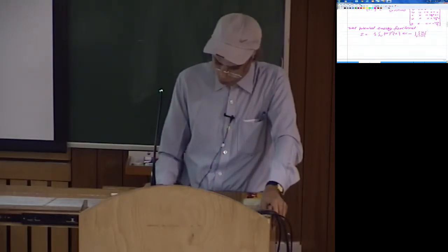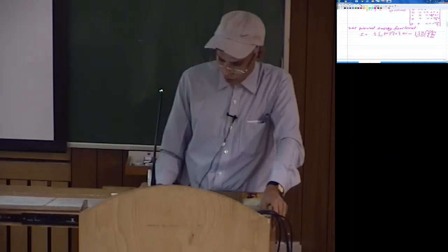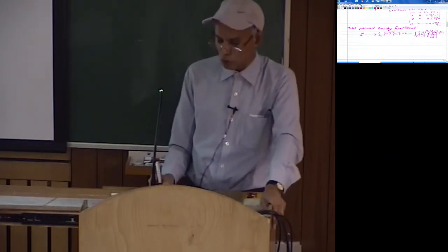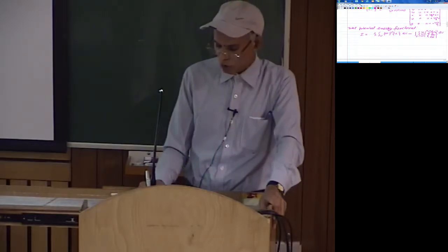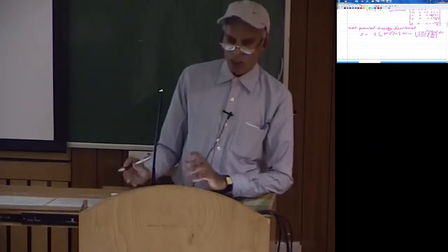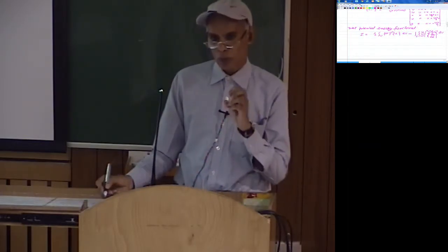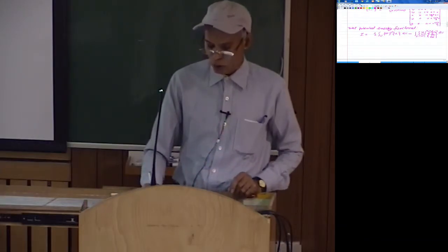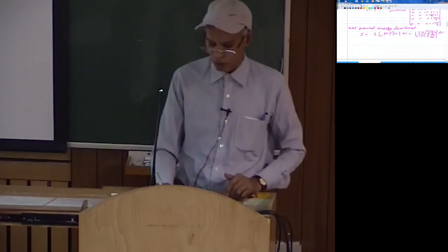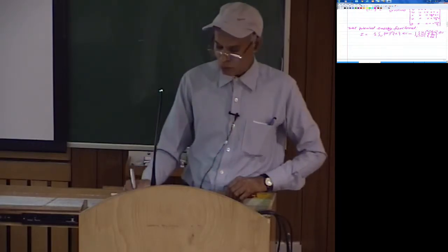So I can write the potential of those as integration over Fbx, Fby, Fbz, and then this is dV. So this is actually Fbx into u plus Fby into v plus Fbz into w. So Fbx, Fby, Fbz are the forces per unit volume. So into dV gives you the total force over a differential volume dV, then into u gives you the work done, negative of that gives you potential, and so for the other Fby and Fbz.